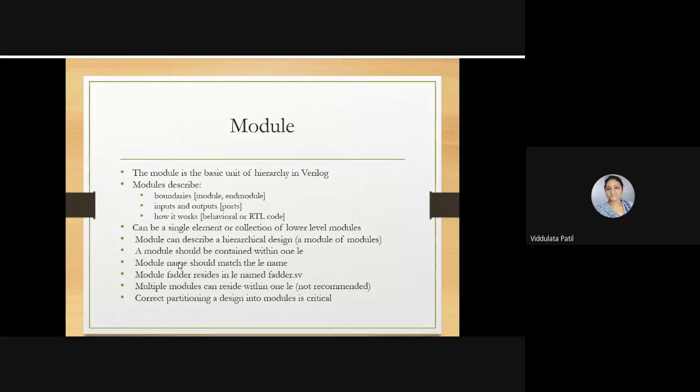Here we need to write a module for the half adder as well as the OR gate. By connecting these modules, we can get a particular module for a certain system, or we can write a single element. So in both ways, we can write a program.